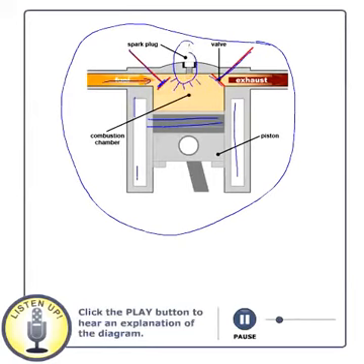Now let's see in sequence what happens in this cylinder. This piston basically moves up and down. So the first step is to bring the fuel and oxidizer, or air, inside the mixture. So this valve opens up. This valve, of course, is closed, and this fuel and air mixture comes in as this piston is pushed down.